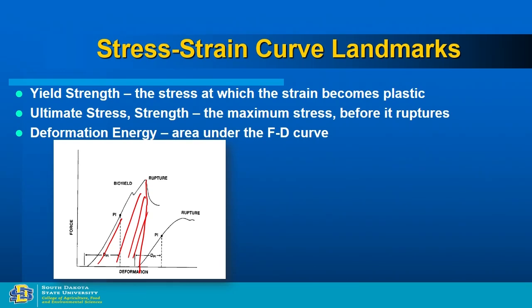Different textbooks will give you different ways of presenting information, but these are the 4 or 5 pieces of information you can collect, which will be more useful for comparing different samples. Every time we do the compression test, it's all about how you are comparing sample to sample. These are not absolute values, because we don't know what other people did, what test they ran, or what type of sample they used.